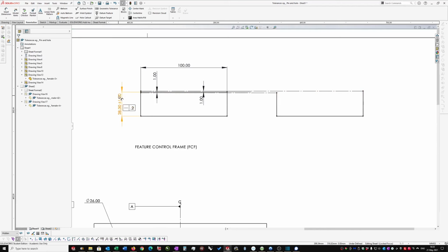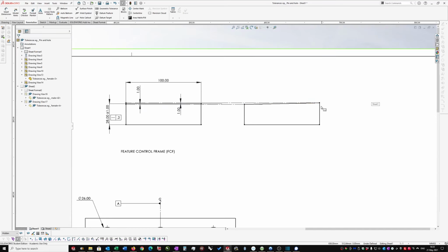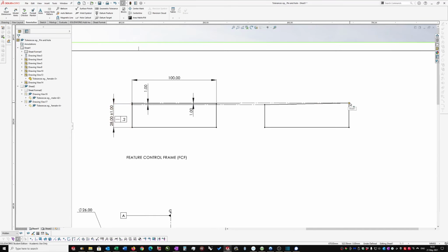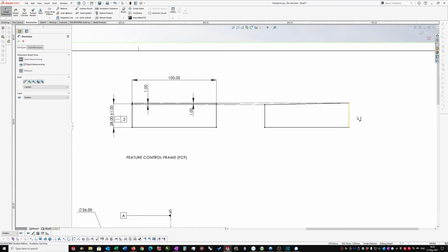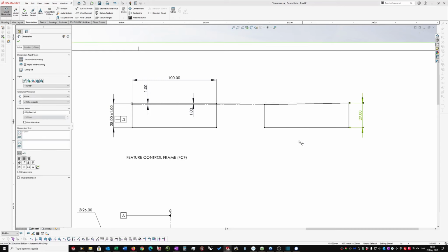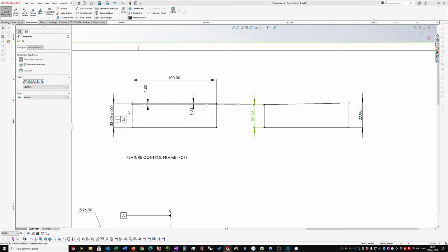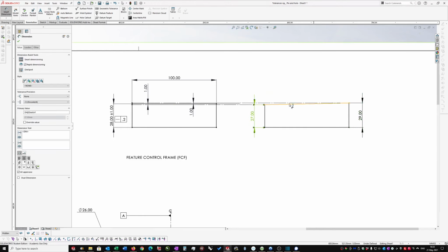So that if I took that tolerance seriously, ignoring what this box says, I could legitimately create a part with a line that looks from the side like this, because 29, which is the height here, let's just dimension that quickly, is 28 plus 0.1, and 27 on this side is 28 minus 0.1. So that's actually what you can get if you have this.